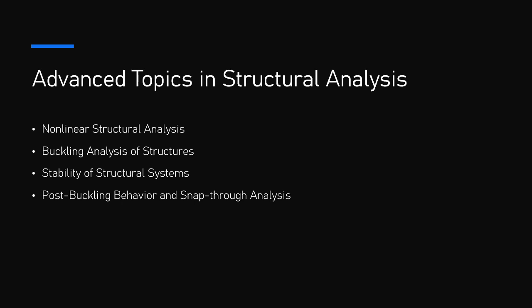2. Geometric nonlinearity. Large deformations. When displacements are large enough that the structure's geometry changes significantly, the linear assumption of small deformations no longer holds. The structure's stiffness matrix changes with deformation, and the equilibrium equations become nonlinear.